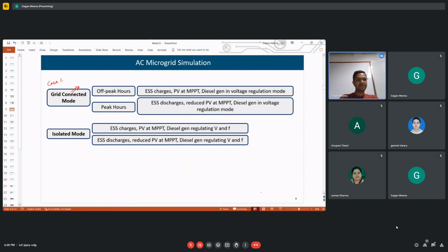we have different buses, and let's say these different devices are present at different buses. I think these are the buses. So if three devices are present at three different buses, each of them will be working only on the voltage at their respective buses. Suppose this is V5, V1 and V22. So the voltage regulating devices available at these three buses will be regulating the voltage at their respective buses only.